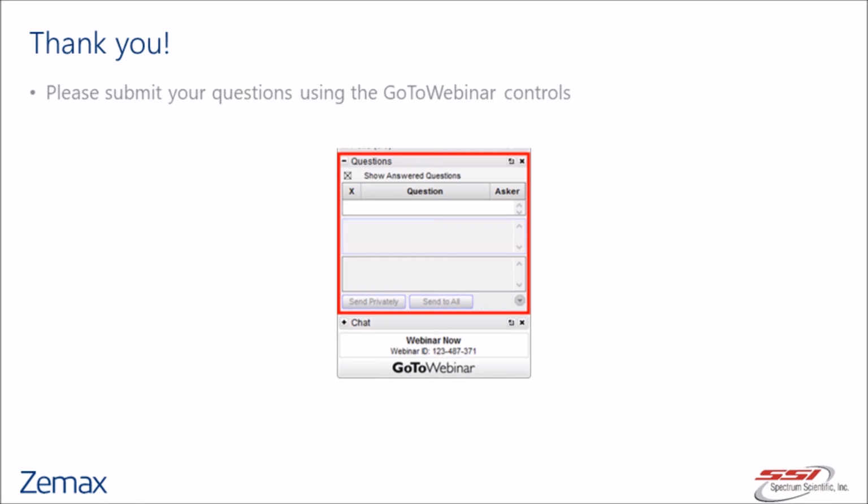That said, you always try to design with the minimum number of terms. There's no reason to put extra terms in your system that don't really improve the performance and just make life harder for the manufacturer. So I think it's fairly rare that you would end up with hundreds of coefficients on an optic, just because those higher order terms stop affecting your performance at some point.